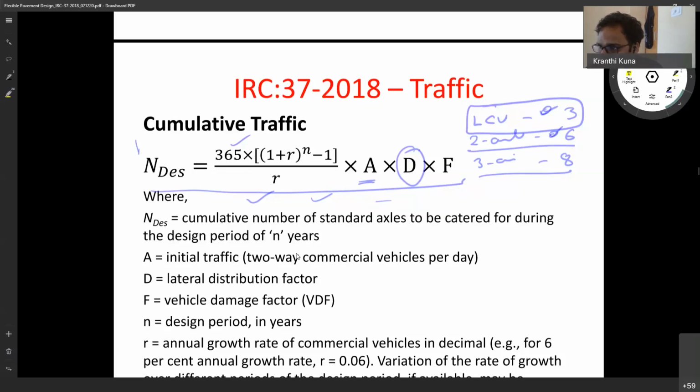Sir, give an example of a quarry. For LHS, suppose the vehicles carrying material out from the quarry are loaded, while those going into the carriageway are lighter vehicles. Then we consider different equivalent load factors, and the pavement designs are different.